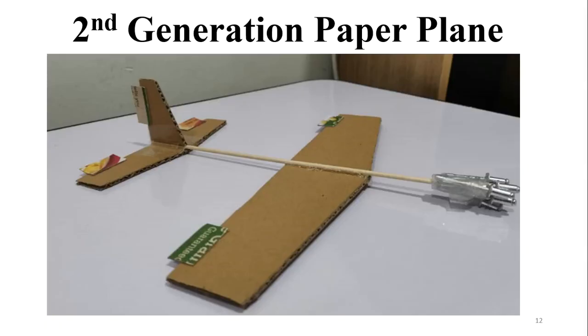So, I redid the plane with corrugated cardboard for the wing and tail. I still use the grey cardboard for the control surface, as it's easier to deflect them if needed. There are a total of 6 rivets as a weight ballast, so the center of gravity is far in front of the AC location, which makes my aircraft more stable in pitching motion.